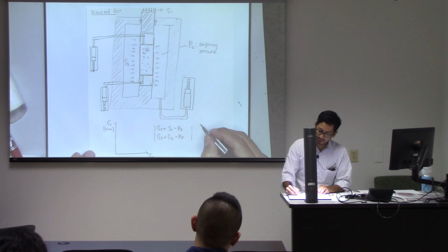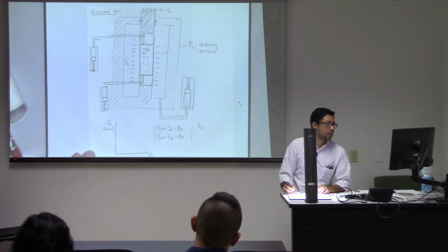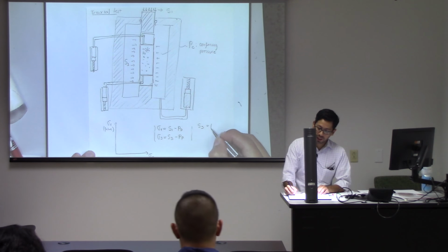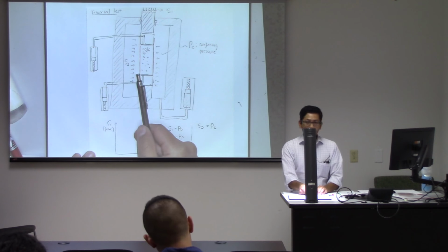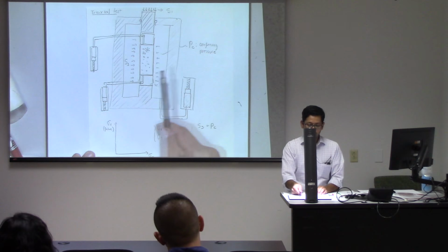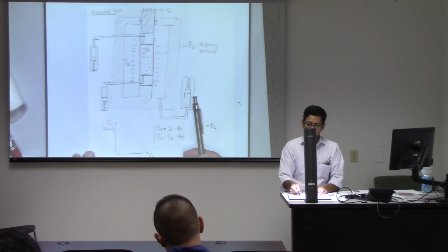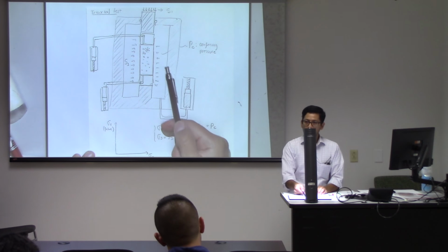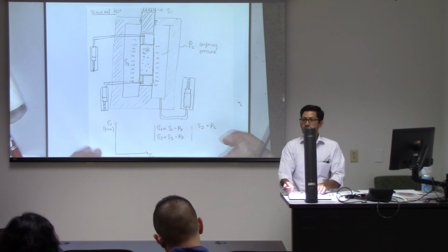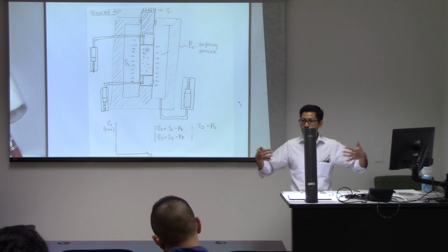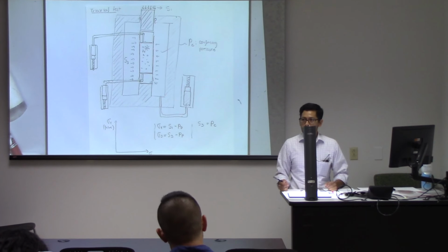What is going to be the value of S3? The confining pressure, right? Notice that the way that we apply S3 is through this membrane and is controlled by this pump. And we apply it with pressure. But when it goes through the membrane, it transforms into a stress.